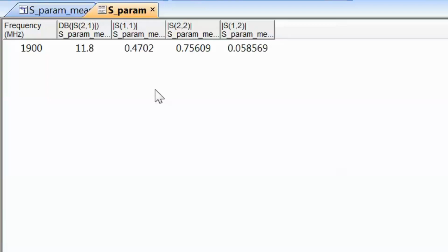Now the important issue here is that we cannot actually consider the input and output ports, and hence the input and output impedances, as separate, because our S12 is not 0. The S12 gives you a measure of the interaction between input and output. So you've got a parameter that shows you how much power can flow back into the input port from the output port.